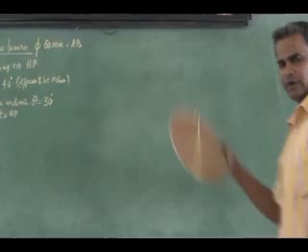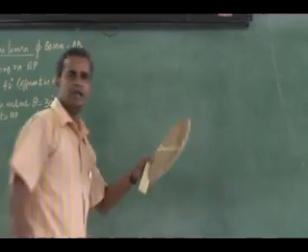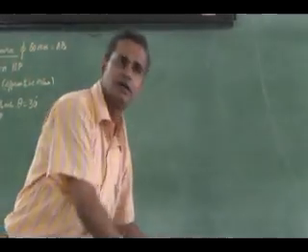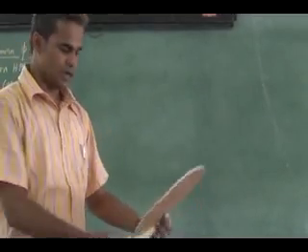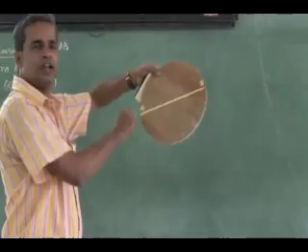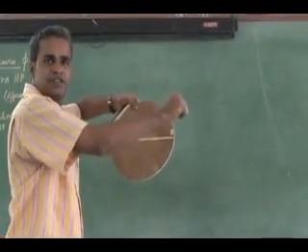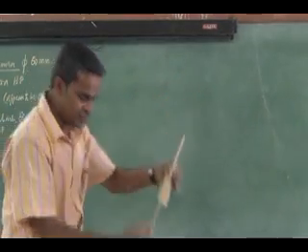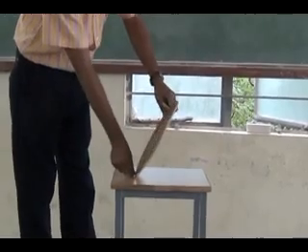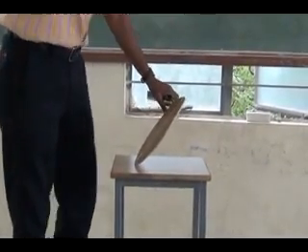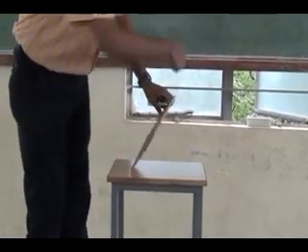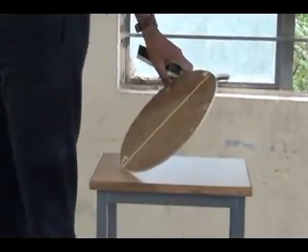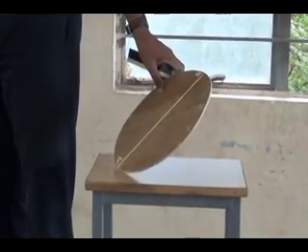Follow the previous one. I have diameter AB, circular plate. See here, the circular plate is resting on HP, so HP in the sense from horizontal plane, it is resting with a corner. This is the diameter AB. It is resting with circumference point A. This A is going to rest on the horizontal plane, and the surface of the plate is 30 degree inclined to HP.